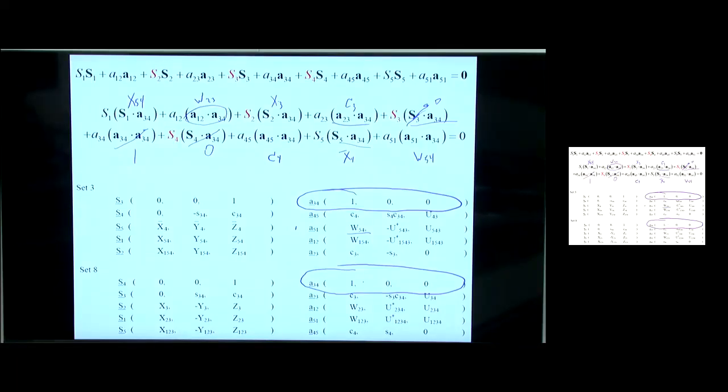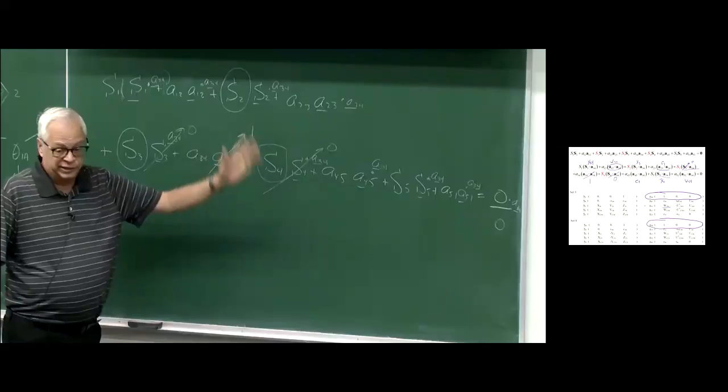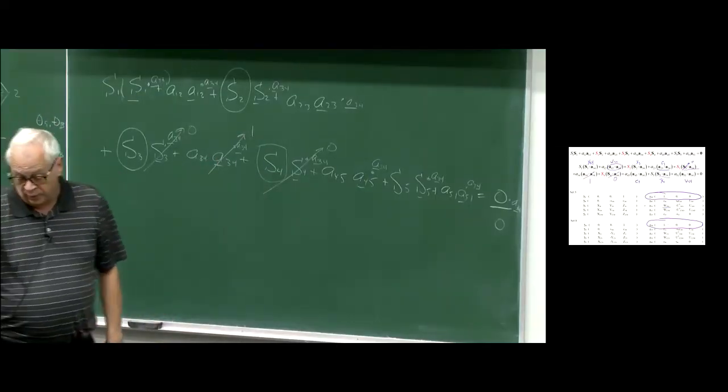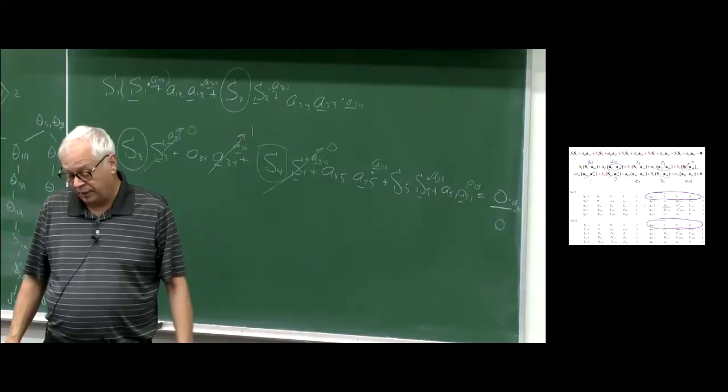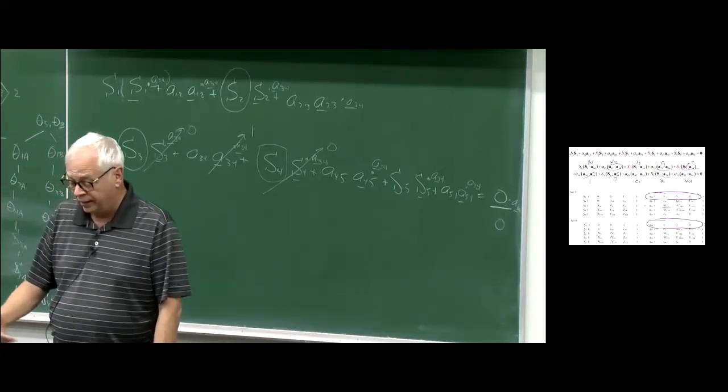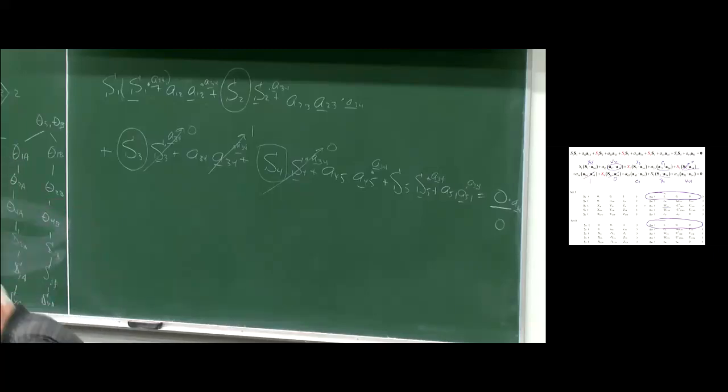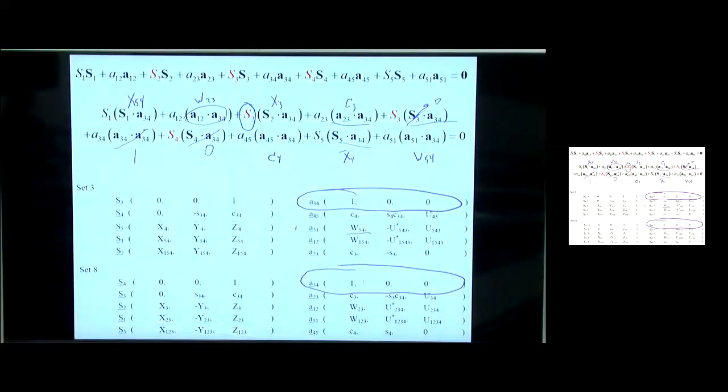So this other way to attack this problem of getting the A and the B case of those joint offsets was to take the vector loop, and I decided to dot product every vector with something that made two of the unknowns disappear. So the equation that we have up there with everything in purple, again, I'll take the given theta 5, the given theta 3, and the A case for all the other angles. And I will wind up with one equation in that unknown, and I'll get S2 the A case. I'll take those same two equations, I'll put in the given theta 5, the given theta 3, and then the B case angles, evaluate everybody, and get S2 for the B case.